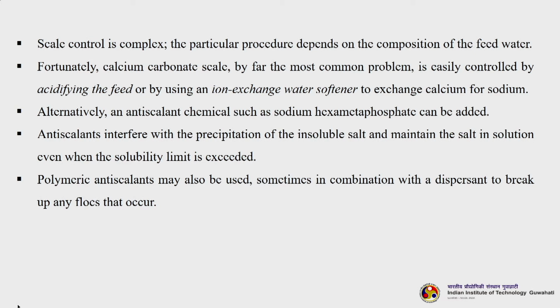Alternatively, an anti-scalant chemical such as sodium hexametaphosphate can be added. This will help in reducing scale formation. It will bind to the scale forming compounds, and those can be removed or recovered from the feed water. Anti-scalants interfere with the precipitation of the insoluble salt and maintain the salt in solution even when the solubility limit is exceeded. Polymeric anti-scalants are also nowadays available, sometimes in combination with a dispersant to break up any floc that occurs in the feed water.